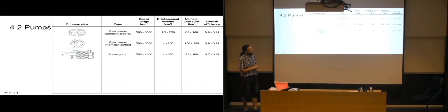So those are the screw pumps. The basics here is that the fluid comes in on one side, and the only contact between these two shafts is right here at the middle. So all of the area between the threads here can be filled up with fluid and will be, just like an Archimedes screw, transported over to the other side where it can exit.